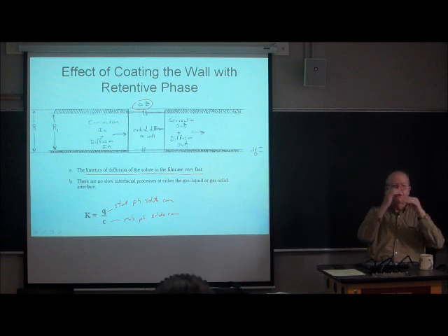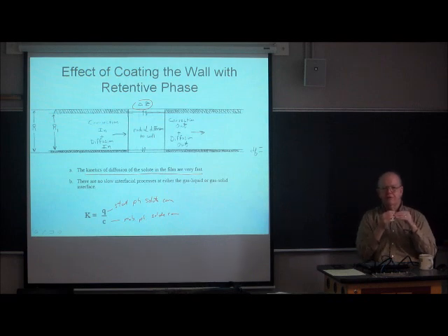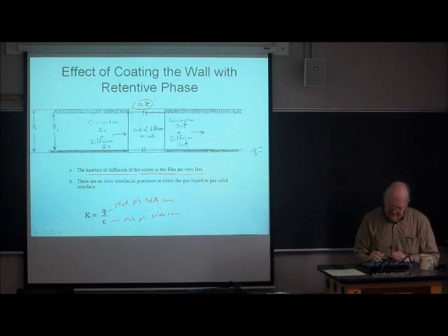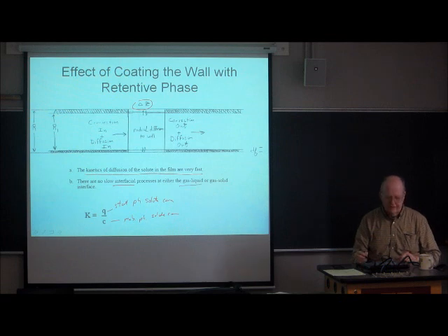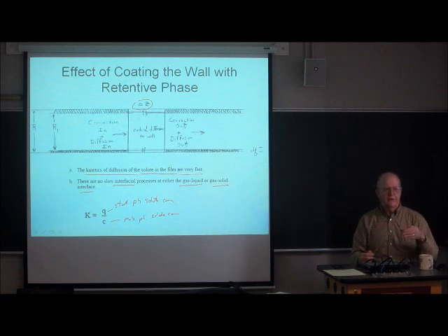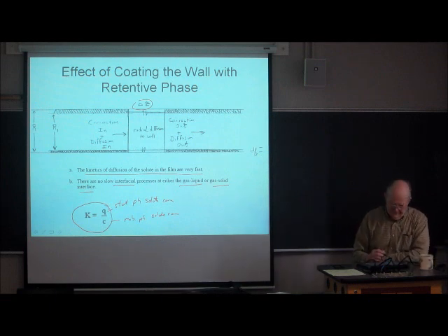There's another assumption, and it's a chemical issue more than a diffusion or a mass transfer issue. When a substance crosses an interface between a gas and a liquid, between two immiscible liquids, there's an interfacial impedance that resists the solute going from one phase to the other. We're going to assume that this interfacial process, anywhere in the system, either gas-liquid or gas-solid interface, is really fast, so that the solute is always in equilibrium between the mobile phase and the stationary phase.